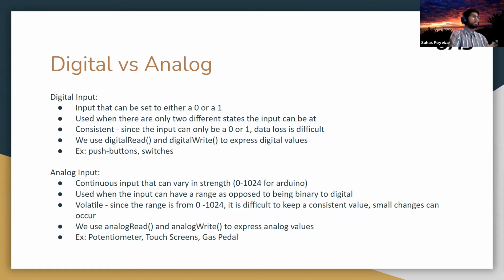So typically when we're working with analog inputs, we want to give a range in which an action can occur. Otherwise, if we give it very specific points, it'll be harder to hit those states and get the intended output for the overall process.